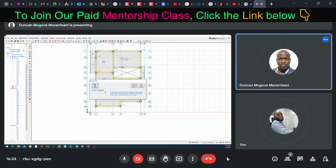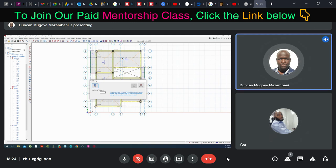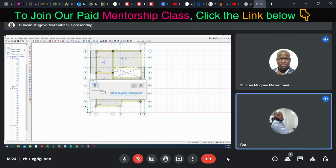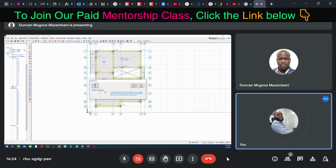Now this software takes the ground floor to be story one. So now you're going to put story two. If you're designing for a one-story building, you have to put story two. For a two-story building, you now put three. Right now you can see that we already have story one active. Ground floor is story one, while the first floor is story two. So you have to put the number of stories to be two, and then click on OK.